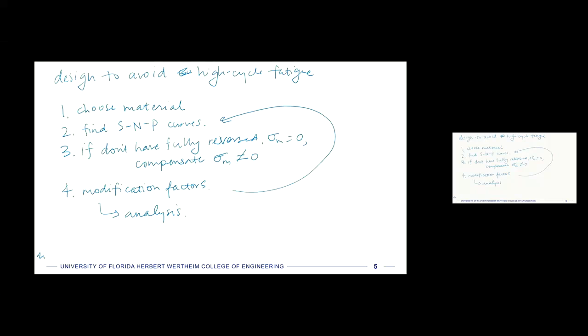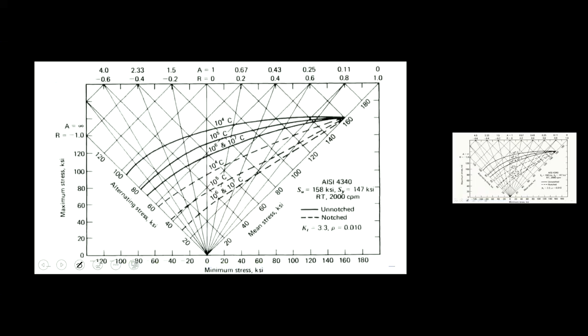Just to be totally clear, you wouldn't apply those modification factors to some effective stress if you did not already compensate for the non-zero mean stress, right? So just try not to get these out of order. Okay, so now let's talk about the influence of non-zero mean stress.